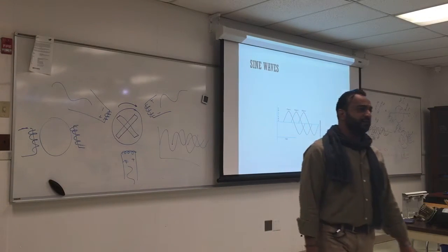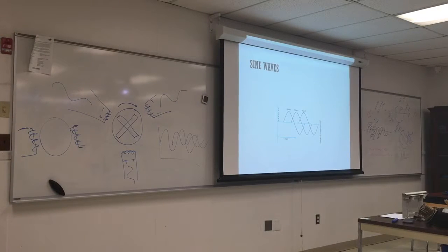Why do we need to know about three phases? Because the layout is different than one phase and 120. So 120, how many hot legs do we have? One hot leg, one neutral, and a ground. That's 120. 220 has two hot legs and a ground. No neutral. So remember that.